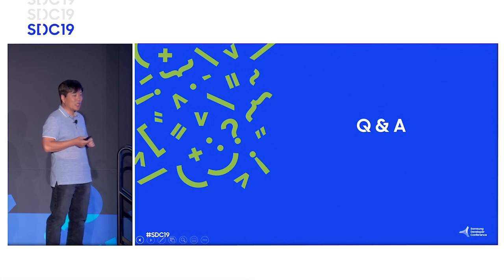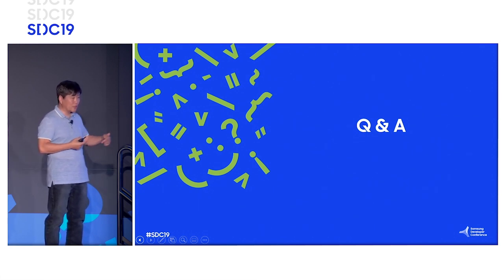So based on that requirement, we built a special SDK which can generate HDR10 Plus by feeding the live 4K 10-bit content input, and then generating the metadata. The encoder company had a way to combine the HDR10 Plus metadata and the frame with real-time encoding. And so the FPS is 60 frames per second with the 4K 10-bit PQ processing result.